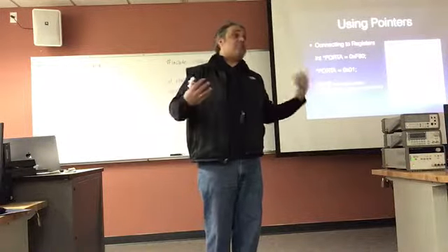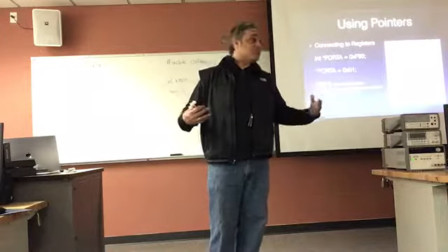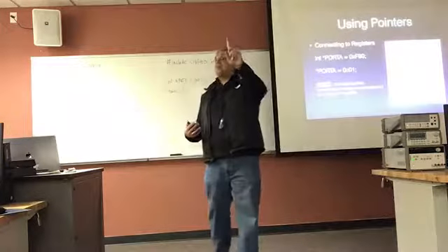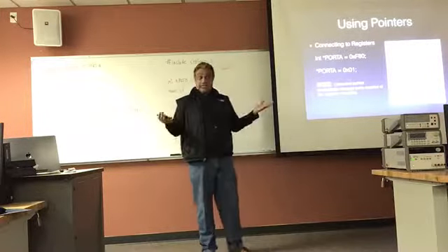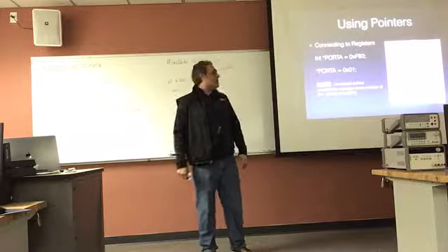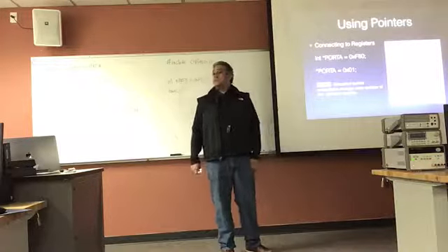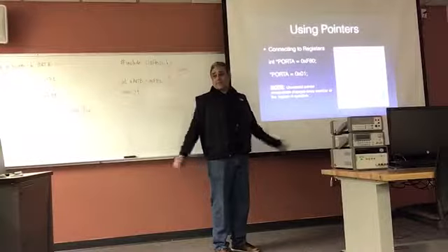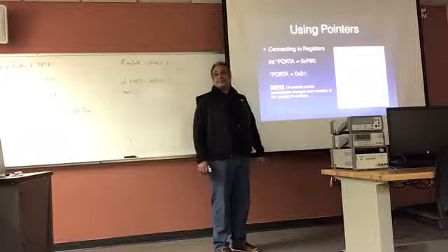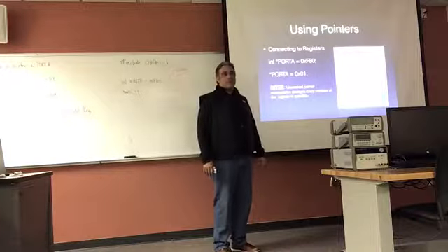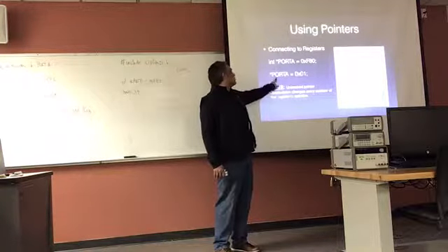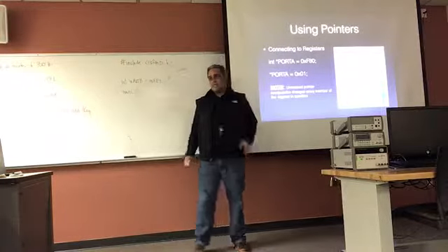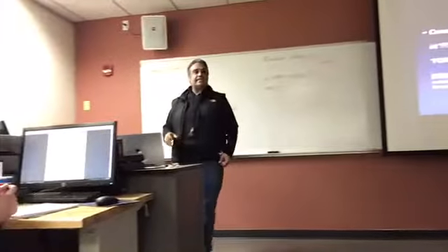It's an 8-bit processor. Therefore, every register contains 8 internal circuits. And so for every unmasked operation, you're going to get 8 changes. All right? Sometimes that's what I want to do. But sometimes that's not what I want to do. And therefore, I need bit masking. That's the only reason why we're using bit masking: so that I can gain access to some of these elements, but not all. Okay? So that's the idea. Any questions so far? Is it making sense?